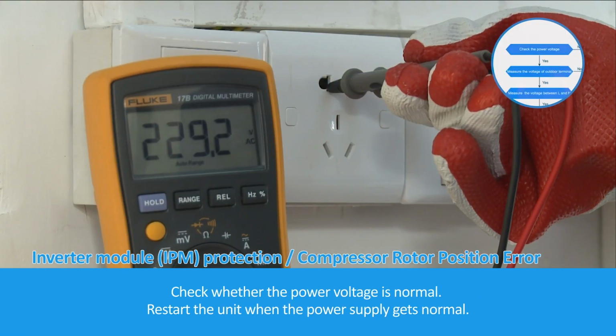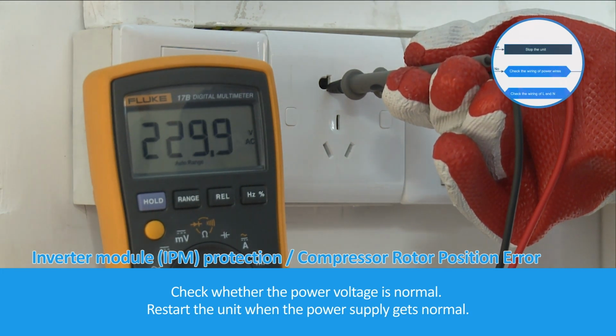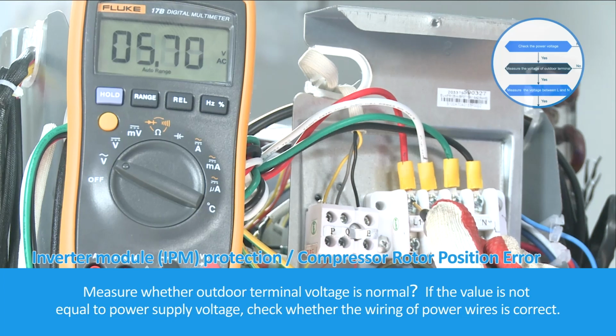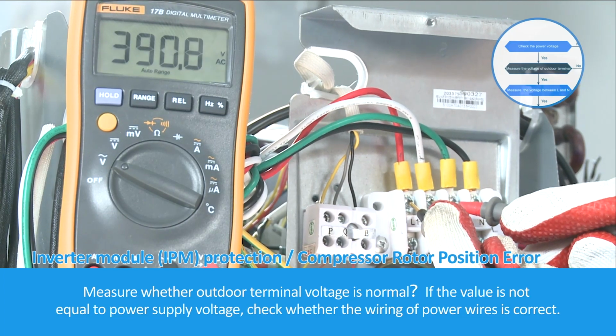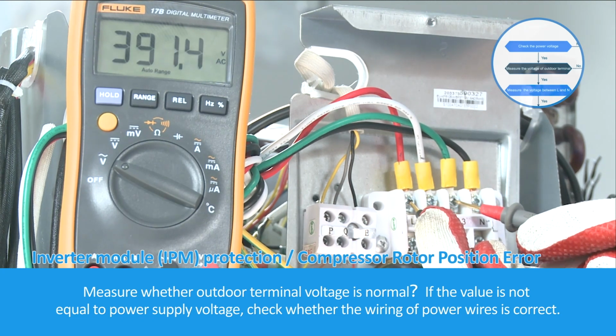Check whether the power voltage is normal. Restart the unit when the power supply gets normal. Measure whether the outdoor terminal voltage is normal. If the value is not equal to the power supply voltage, check whether the wiring of the power wires is correct.